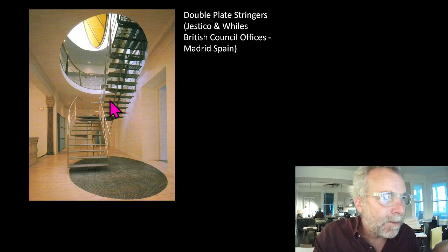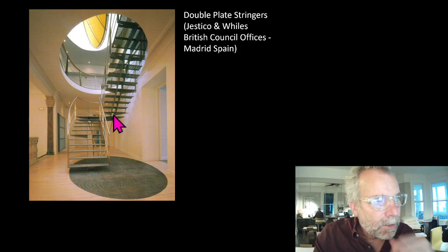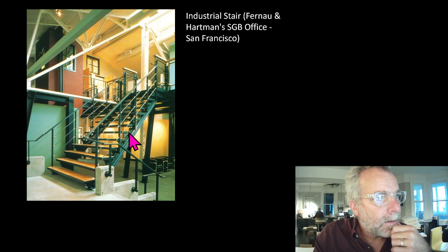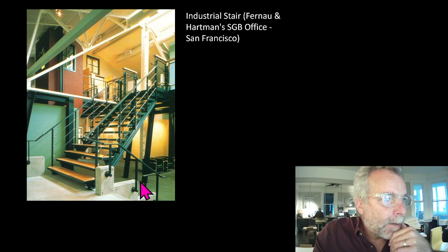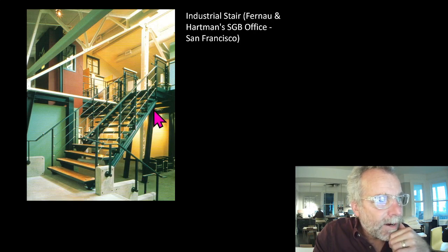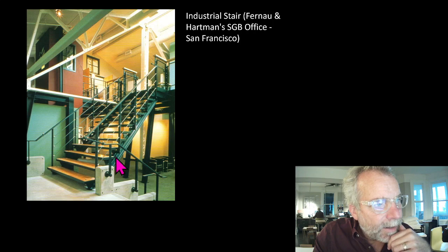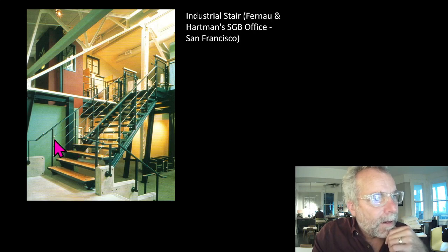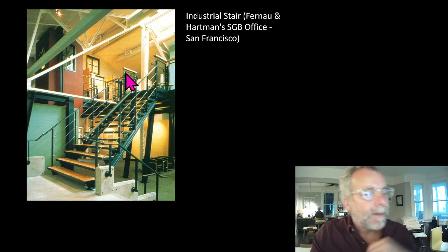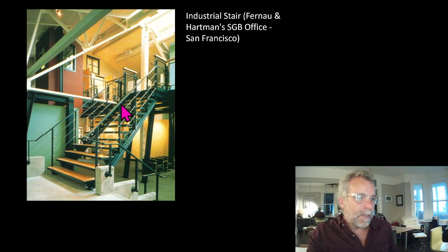The canopy outside the Fields Institute, right next door to 230 College, the old architecture building, used a similar strategy. Very tectonic, very industrial stair. So this one has a channel that is under the treads. The treads sit on top, or maybe it's a wide flange beam. The treads sit on top, and it looks like a tension rod in the guard. Again, climbable, open riser, not a contemporary stair, but a very, very clean, simple design.